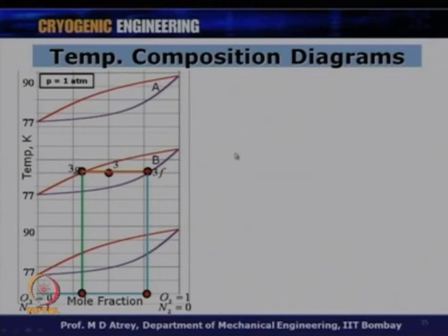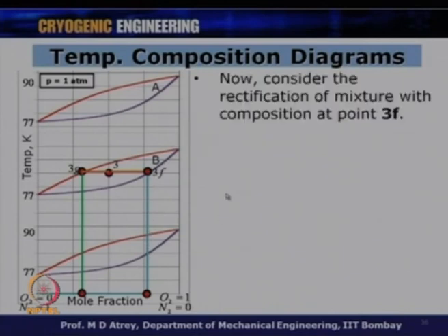Now, what I am going to do is take this liquid from here. This is my first process in rectification. I am going to take this liquid, with these molar fractions of liquid plus gas, and enter the same temperature composition curve again. So I will get some vapor fraction added to this. I got a two phase mixture again, and this liquid plus vapor will enter the same temperature composition curve at this point now.